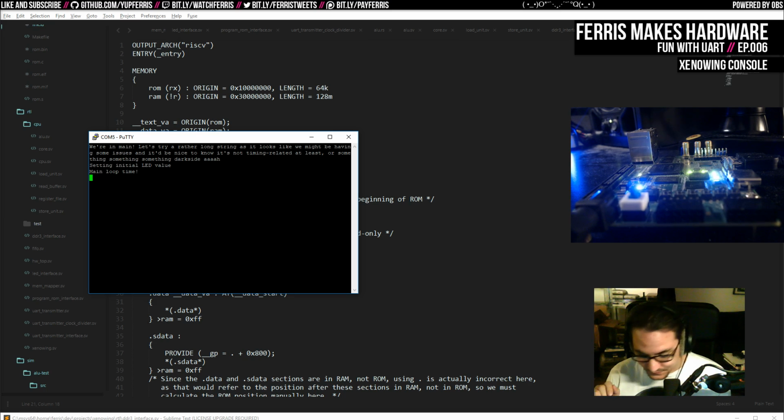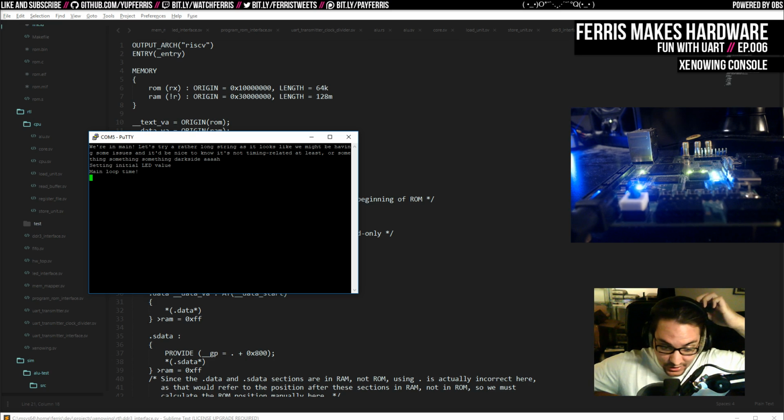The second reason is I'm thinking for that, and even a little bit more ahead, and also just to ease debugging for myself, I would really like a way to live reload code in this thing. So the only code that actually exists here is ROM. But what I'm thinking that we can do is just add in a separate hardware unit, because this UART goes both ways, right? So there's a transmitter and there's also a receiver.